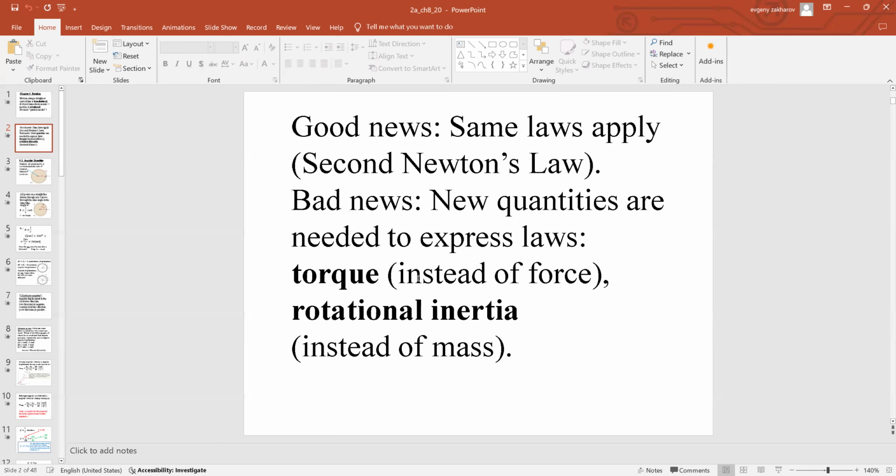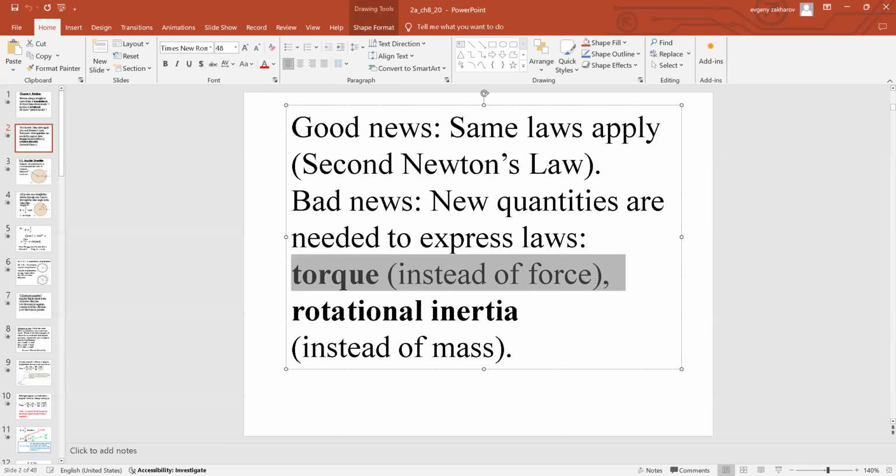The analog of force is going to be the torque, and the torques are a little tricky, but still a straightforward parameter that you can easily calculate if you use the line of action and moment arm approach, which I'll explain later, and just keep track of positive and negative values for clockwise or counterclockwise rotation.